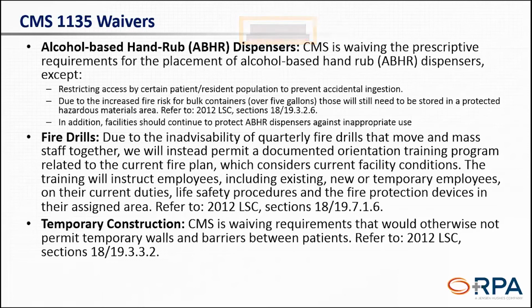Temporary construction partitions, where typically we're not allowed to use temporary partitions between patients. CMS has granted an allowance where you can use temporary walls and partitions that may not be truly fire resistant materials. So some more guidance there in that particular section 19.3.3.2 for what exactly that goes into. But that's basically allowing where we can have some different type of materials being used to separate patients from one another.